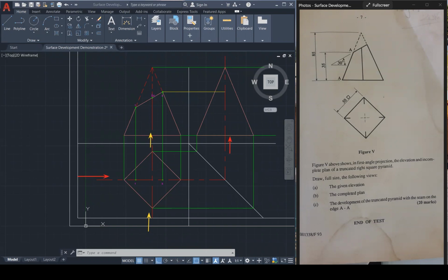So I'm going to deal with the elevations with the red arrow now. So I need to locate point 1, which is here. If I'm looking here, point 1 and 3 have to be somewhere on this line, like here for 1 and somewhere up here for 3, right? Based off of this information. Standing right here and looking, you're going to see a low point here, and then you're going to see a high point here, right? Because this is low, that is a high point here. So we already know that.